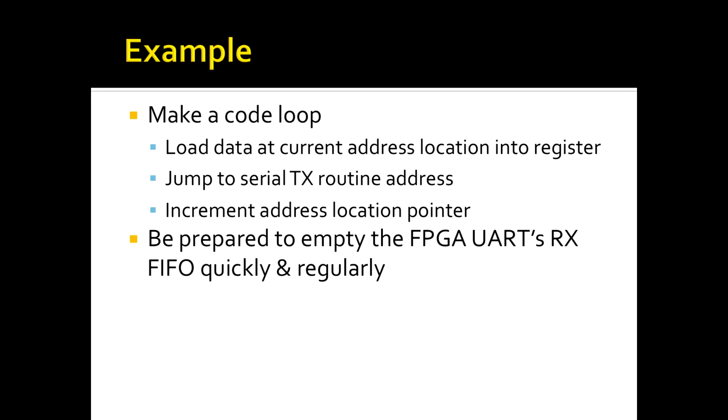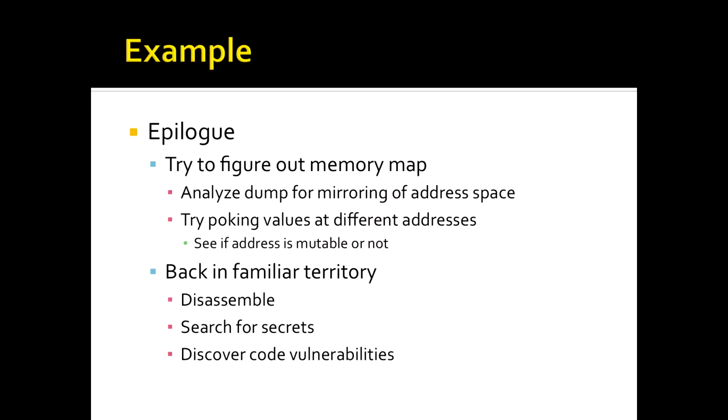And you have to be prepared to empty the FPGA's receive UART buffer quickly and regularly, because basically the entire code and data space in this particular chip will be dumped out in an endless loop. It'll just keep mirroring and wrapping over the address space, and this is what's known as linear code extraction.